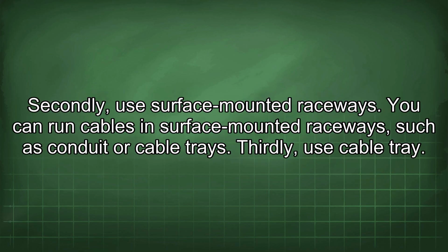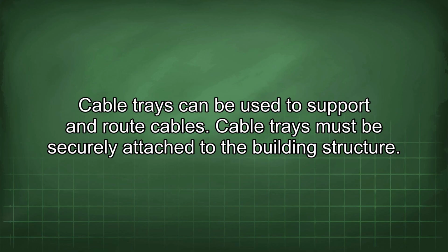Secondly, use surface-mounted raceways. You can run cables in surface-mounted raceways such as conduit or cable trays. Thirdly, use cable tray. Cable trays can be used to support and route cables. Cable trays must be securely attached to the building structure.